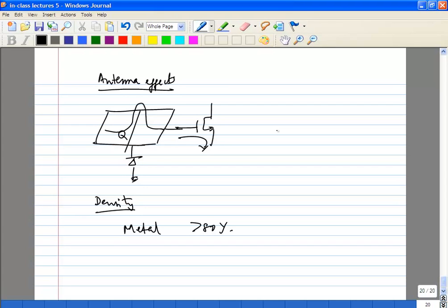This is very typical. Rather actually, yes, that's right. So it could be 80%. Let's say 80%. So you could have requirements like this. Obviously your circuit routings and everything are going to contribute maybe 10% or 15%, probably not much more. So if you want to make this up, you'll typically have to do what is called fill for your transistors.